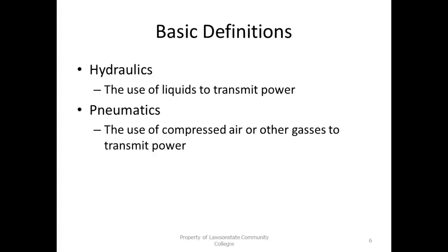Yeah, these slides are up there. So hydraulics is when we use fluids to transmit power, and pneumatics is when we use a gas to transmit power. Now, by far, the most popular gas is air, which actually is a combination of gases. What do you say, Justin? Yeah, it's cheap because it's there. And like I said, in some applications, in extremely cold environments, we don't use air, we use nitrogen. As soon as you use another gas, it's got to be a sealed system, so they become more expensive.